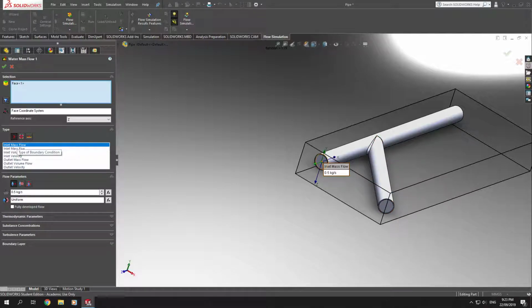And then I pick inlet mass flow. Type in your known values. I just picked some random number here. Substance concentration, so mine is just 100% water, 100% refrigerant. But if you've got a specific mix like 40-50 or 90-10, type that in. Okay, so you would click the tick,